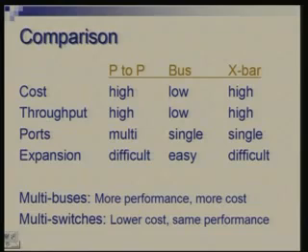So we can organize it in terms of multiple smaller switches and effectively reduce the cost. So what I mean here is that if you have n units, a crossbar will make it possible for anyone to talk to anyone, which means you have n into n minus 1 by 2 pairs. If the number of communicating pairs is much less, then you can incur lower cost. That is the whole idea.